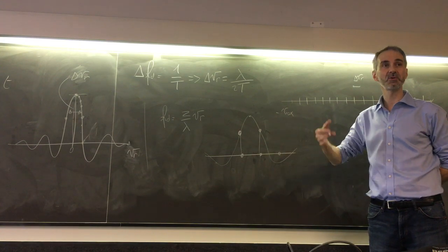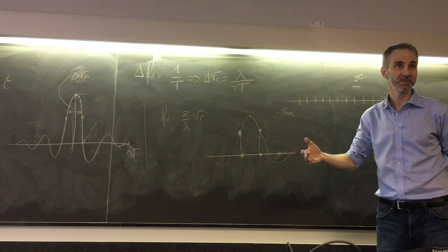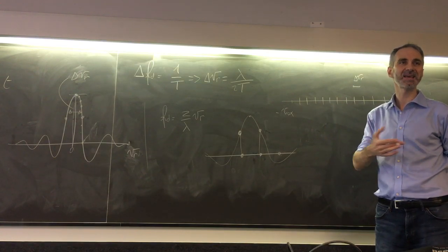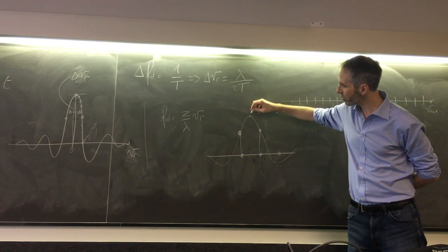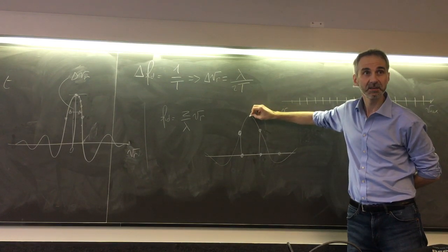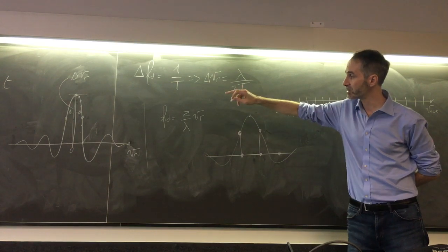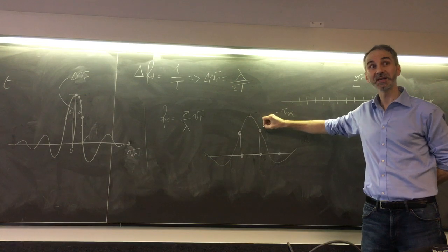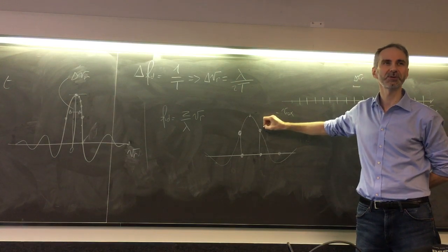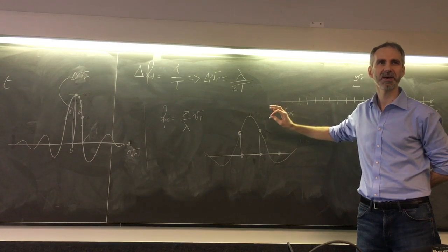The other point is that you always have noise, and noise is the same everywhere. So if you are not taking the peak, but you are sampling this function away from the peak, then you are degrading your signal to noise ratio. Okay? Did I answer better now?